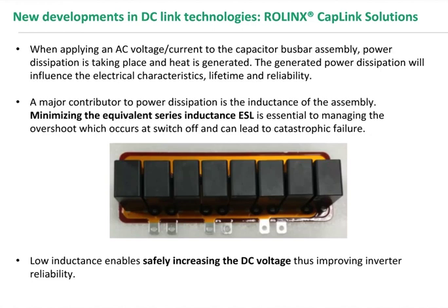What you have in this photo is an example of a capacitor busbar assembly used with a HybridPACK 2, and we have been testing this and already offering it to our customers. Here is an example where you see the capacitors, but it can also be encapsulated, and it has all these kinds of features to connect this module to the other components in the inverter system.